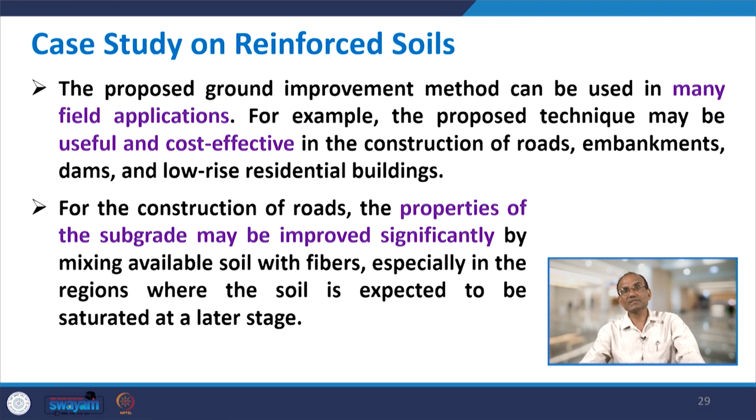For example, the proposed technique may be useful and cost effective in the construction of roads, embankments, dams and low rise residential buildings. For the construction of roads, the properties of the subgrade may be improved significantly by mixing available soil with fibers, especially where the soil is expected to be saturated at a later stage.